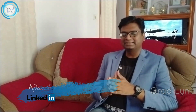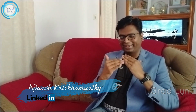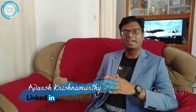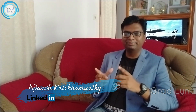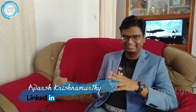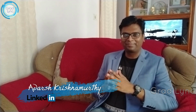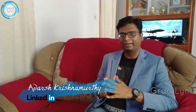These wingtip vortices reduce the angle at which the incoming air is hitting the leading edge. This effect is called the induced effect. Because the angle is reduced, the lift developed will be reduced. Similarly, drag will increase. This increment of drag due to lift is called induced drag. We also call induced drag lift dependent drag.